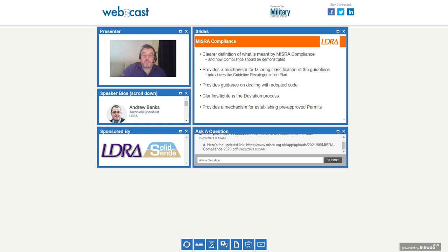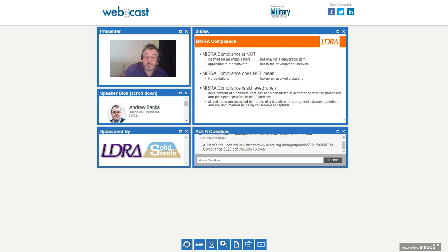We're defining what MISRA compliance is and how compliance should be demonstrated. You can't just say, yeah, I'm MISRA compliant. A new feature is it provides a mechanism for tailoring the MISRA guidelines. Importantly, and specifically relevant to this presentation, it has guidance on dealing with adopted code. We'll explain that. It clarifies and tightens the deviation process, because sometimes deviations are required, and provides a mechanism for agreeing with the supply chain some pre-approved permits which help you with the deviation side.